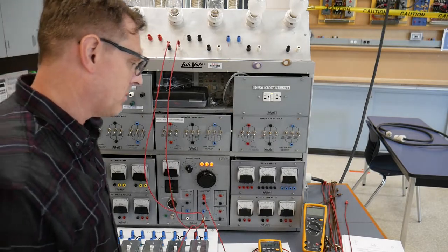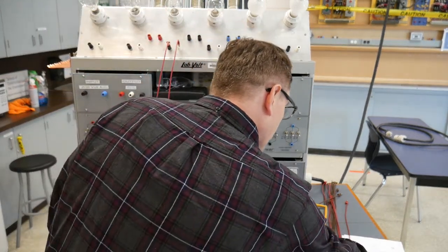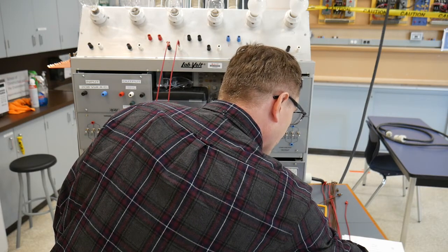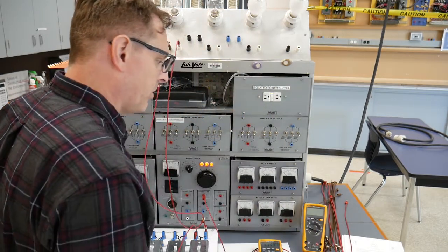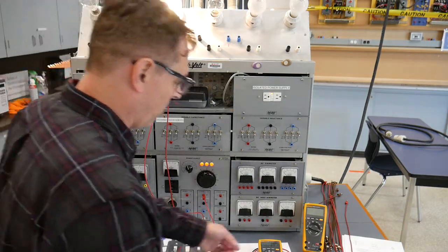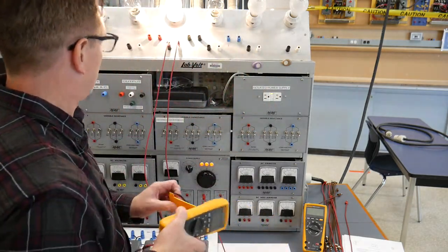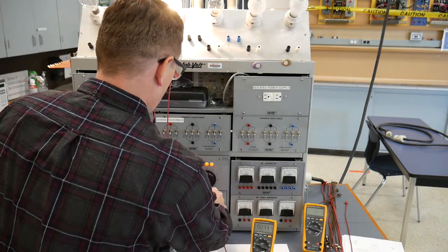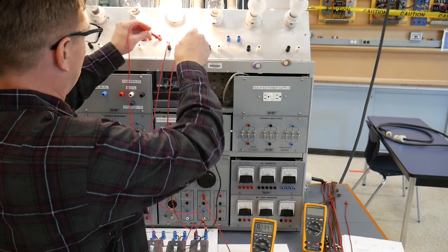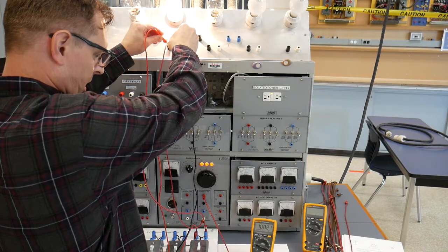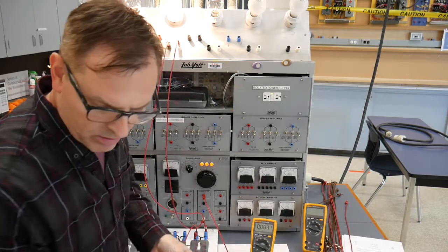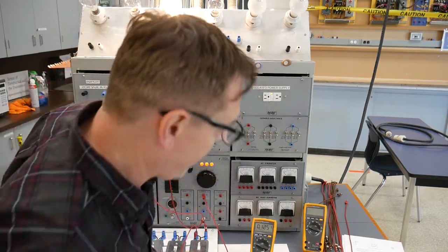Okay. Next, what they ask us to do is to use the voltmeter and measure and record the voltage across each of the following points. So lamp terminals with the switch closed. Closed meaning that the light bulb is on. Okay, so with the switch closed, they want us to meter the voltage. Okay, and we are sitting at 110. Okay, so that's 110 on that.